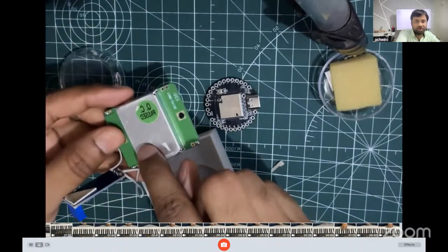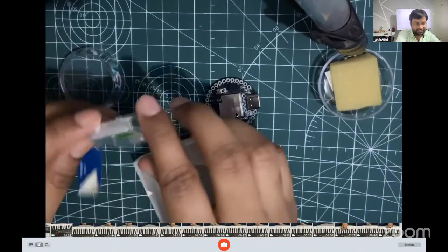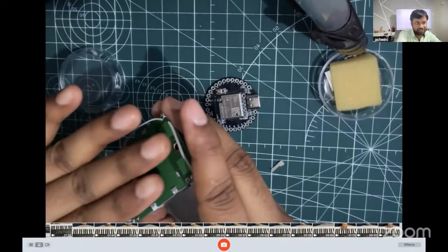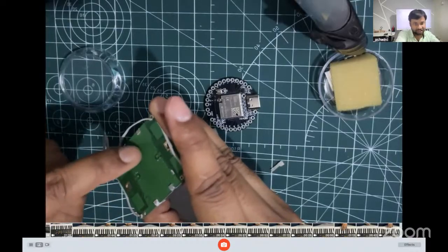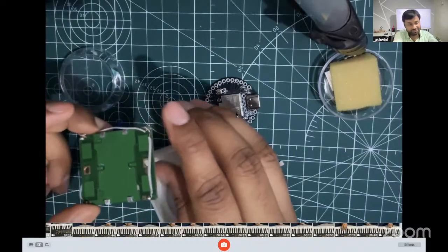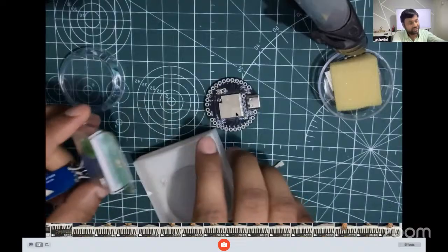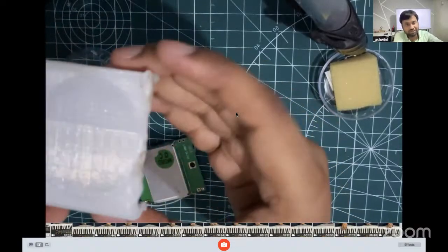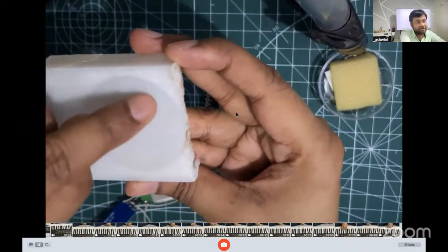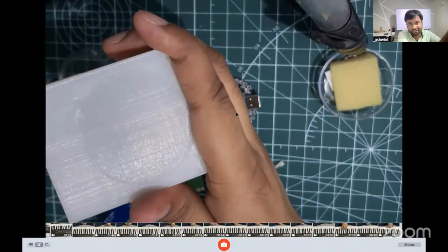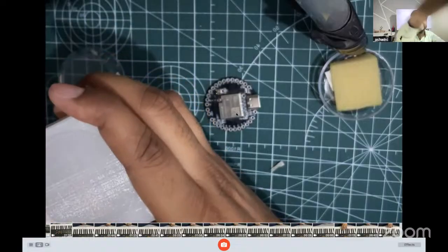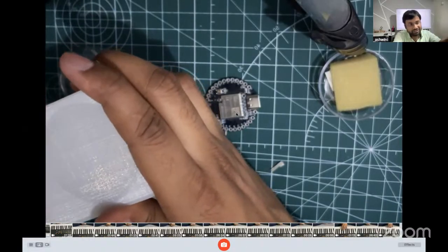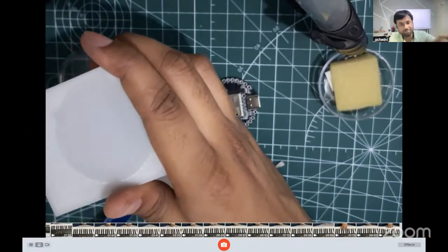And this is not doing any kind of sensing. This side is the sensing side. Okay. So this side is emitting the signal and receiving the signal. You can see these tracks out there for the transmitter and receiver. Whatever device you are designing, you have to make that part thin. Whatever cover or case you have, make that part thin so that it can easily transmit the waves without much loss.